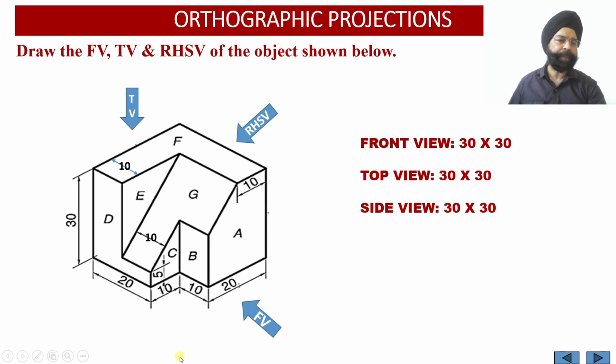So they will be represented as dotted lines or hidden line projections over there, right? The only surface which will be visible from the orientation or position of the observer will be a square face, whereas these faces are lying on the back side. So we are going to get hidden line projections corresponding to surfaces D, G and B.